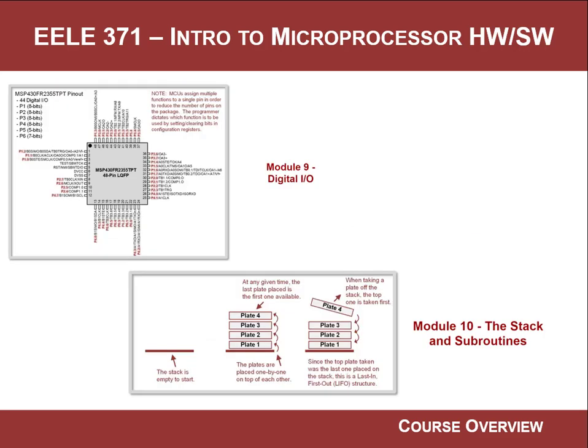Finally, we have all the basics of what the computer's doing, and then we start adding in access to the outside world. We start with our first peripheral, which is digital I/O. Essentially pins on the package where if you write a 1 to it, the pin will go high. If you write a low to it, the pin will go low. And we start driving things to the LEDs and reading from buttons, okay?